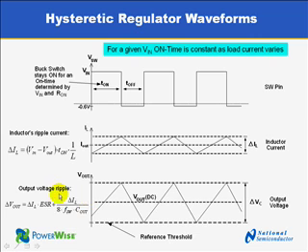So the second term of the output ripple voltage is the one that can cause problems. We will talk about these problems on the next slide. This factor only comes into play if the ESR is very, very low. Example: a ceramic output capacitor. Only in this case, and also with small values of the output capacitor, this factor influences the ripple and can cause some problems.